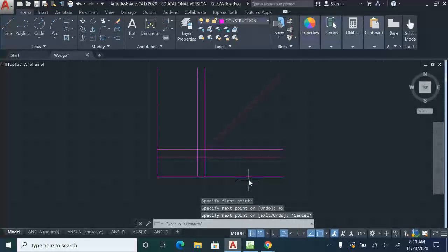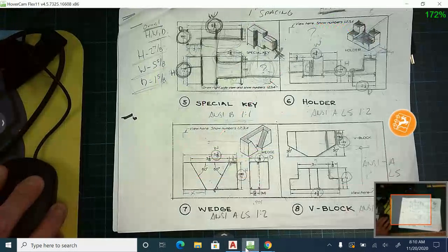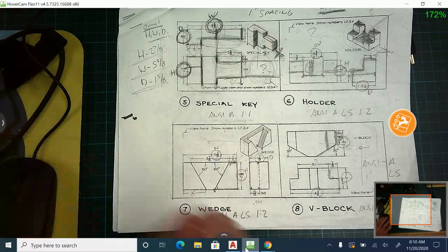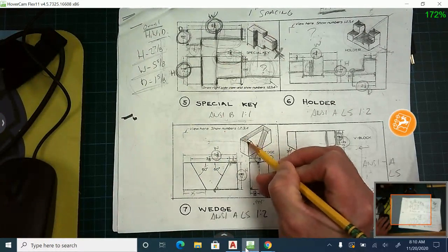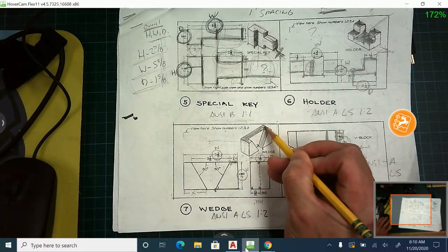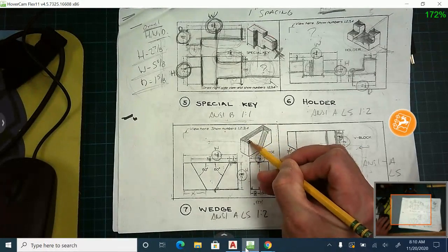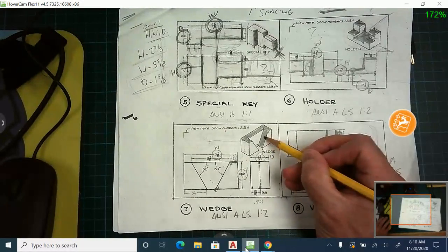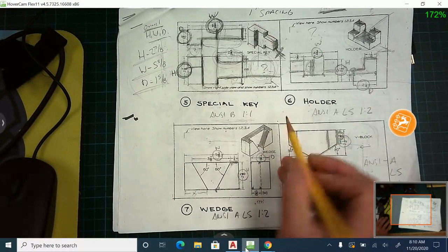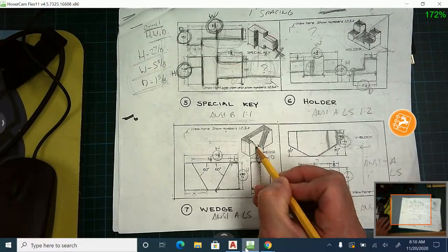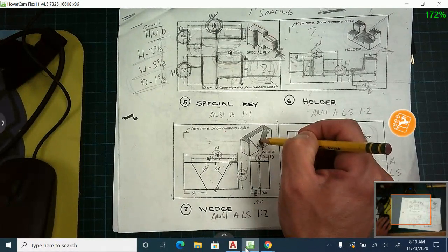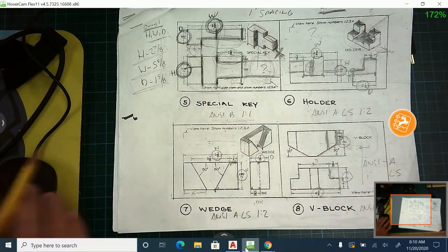And that's going to help us project the right side view up and over to the top, because in this one, we're missing the top view. And I actually shaded in a little bit what I'm seeing if I'm looking down. So I'm going to see this kind of like C shape. I'm also going to see this angled surface. However, it won't be angled looking straight down on it, and you'd see that same surface over on this side too. So we're going to project the right side up and then over.